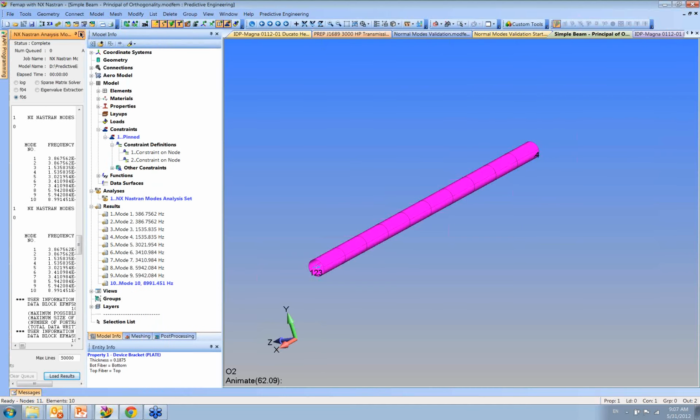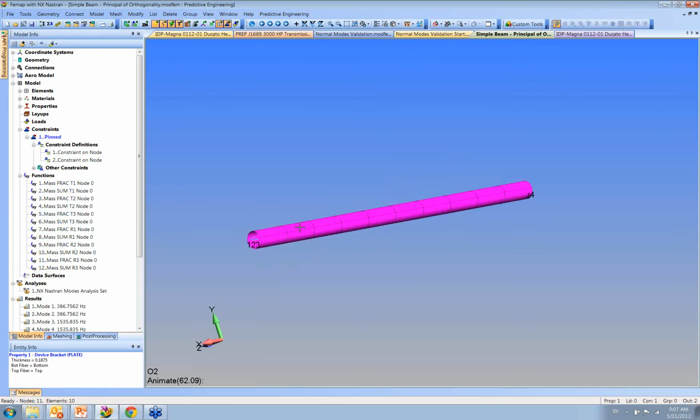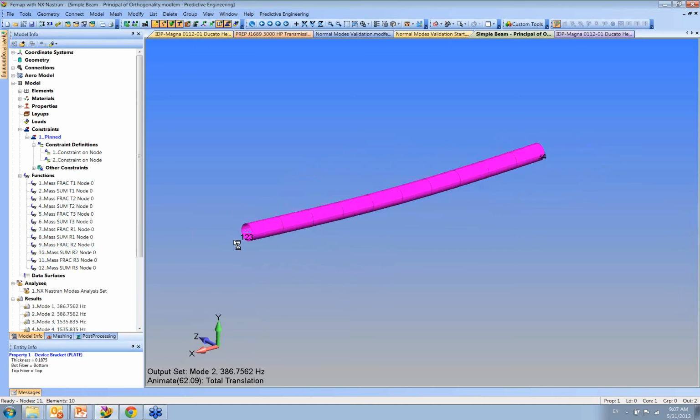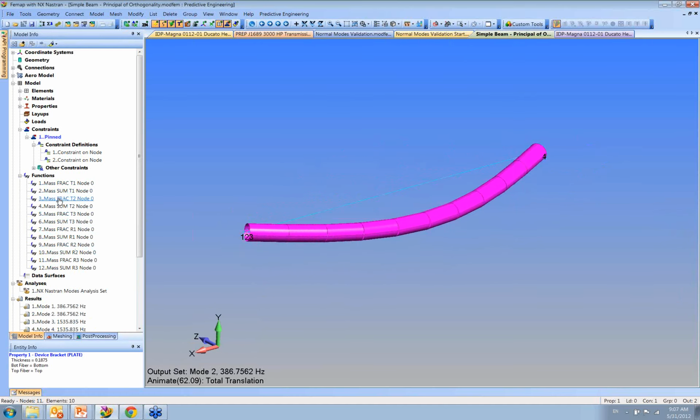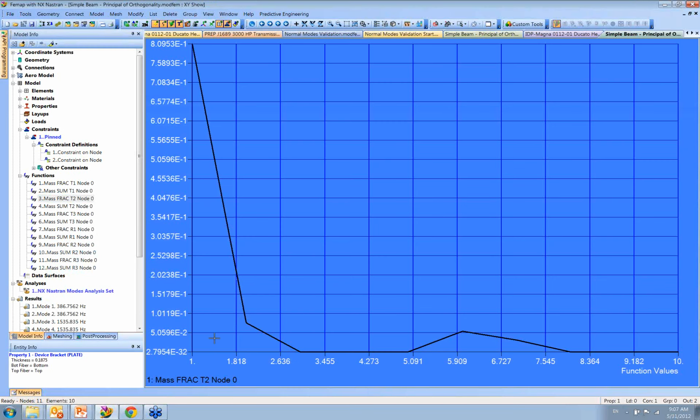I used to do it like that before I got comfortable with looking at the mode. So remember, x is down. We don't want anything to do with that. So let's look at fraction right there. And this is the default legend. So you can see the first mode, you're capturing 80% of the mass of the structure. It is hugely dominant, the first mode, second and third. And likewise, we'll probably see something very similar for that.